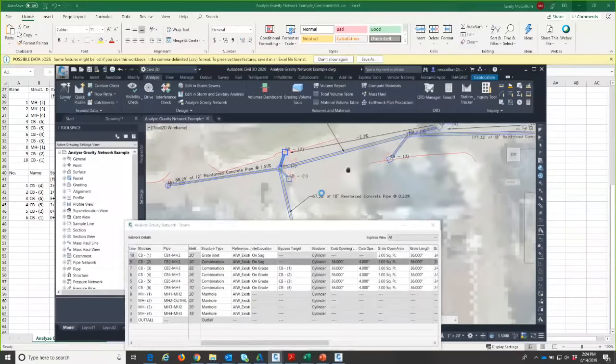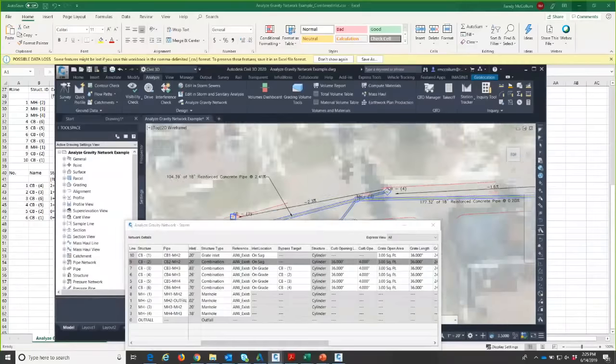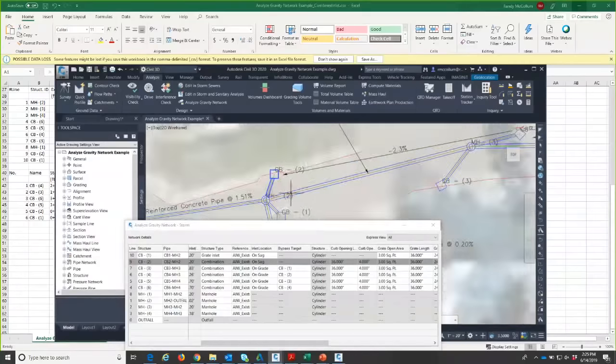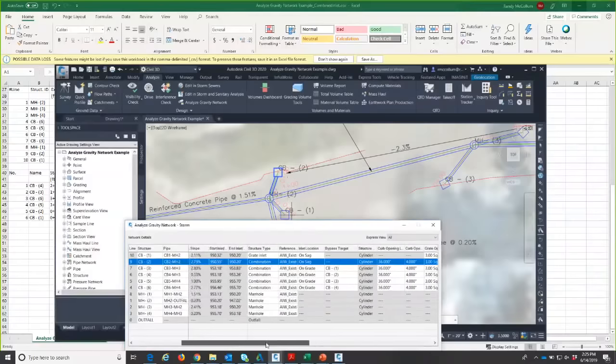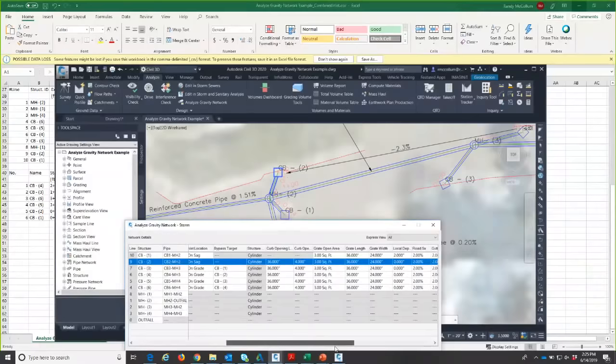So I would have to look at it and figure out, is the issue coming from my overflow? Is my overflow excessive, in which case I may want to redesign my upstream catch basin? Or is the amount of area that I'm trying to drain to here creating such a large queue that I have an issue in this area? I could open the curb up for outside of 36 inches to increase it, but that's going to get expensive quickly.